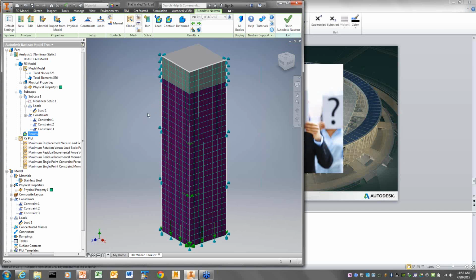My favorite nonlinear one is if you imagine a plate that's fixed on all four sides. One of the assumptions of linear theory is that you don't get stress stiffening. So if I have a plate fixed on all four sides and I push down on it, the plate has not actually moved out of position, so there's no bending in the plate and there's no tensile force in the plate. So the only thing that resists the deformation is shear. So if you have that plate fixed like that and you put a pressure on it, you get a really, really large deflection because there's only shear.